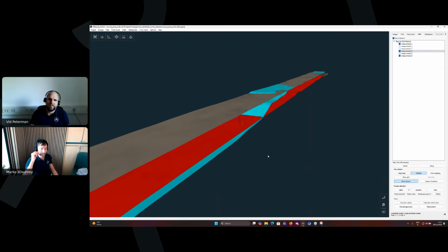Very good, thank you, Vit. And I will say that if you do everything correctly, with a good, powerful camera and enough ground control points, there is no other technology that is so powerful and accurate for volume calculation. The 2 centimeters I mentioned is the average. If you make sure that you have enough ground control points, you can achieve even higher accuracy of the point cloud.